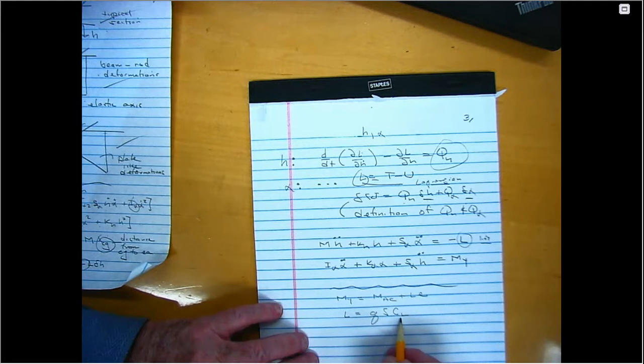The reason we want to define C sub L is because we can reason either from dimensional analysis, or because we know what the aerodynamic model fundamentally looks like, that whatever the lift is, it's going to be proportional to the Q, proportional to the wing area, and then this thing's a non-dimensional number, which will depend on the Mach number. It will depend on alpha and H in general.